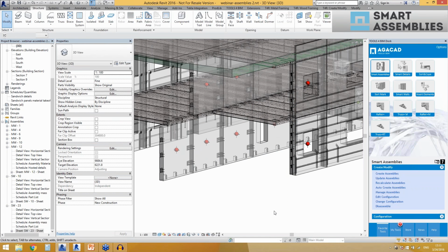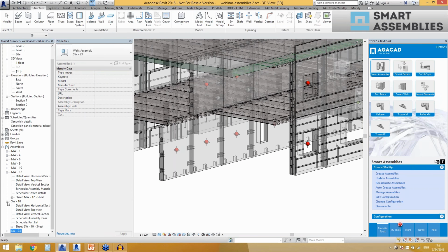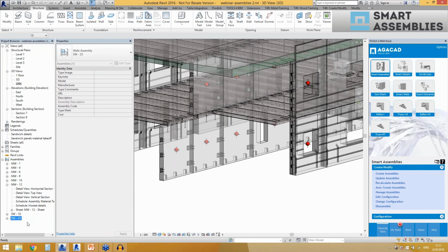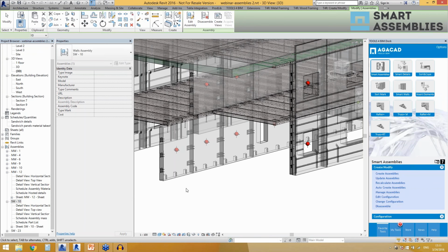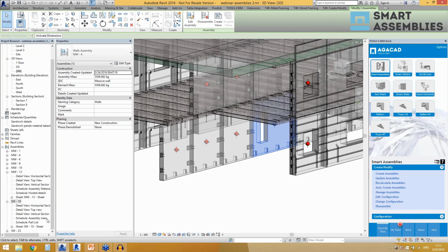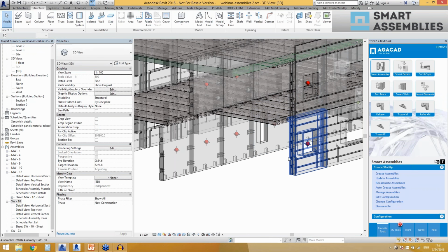So sometimes it's useful not to update drawings because, let's say, I have prepared already all of the dimensions. Maybe I have deleted some of the dimensions. Maybe I did some manual modifications which I want to remain, and I don't want to use update of a view.